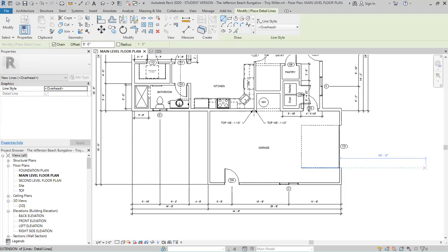Now, another thing I just noticed here on our drawing, going back to dimensions, we didn't have a dimension here, but you'll notice that there is a dimension on the inside here. The way it is written, I'm going to actually move it so it's on the outside. No, I'm going to leave it where it is. The reason it was placed there is because these other strings of dimensions come to the inside of the wall, which, if we were to remove the garage and make this building just a simple square, would be the outside of the exterior wall.